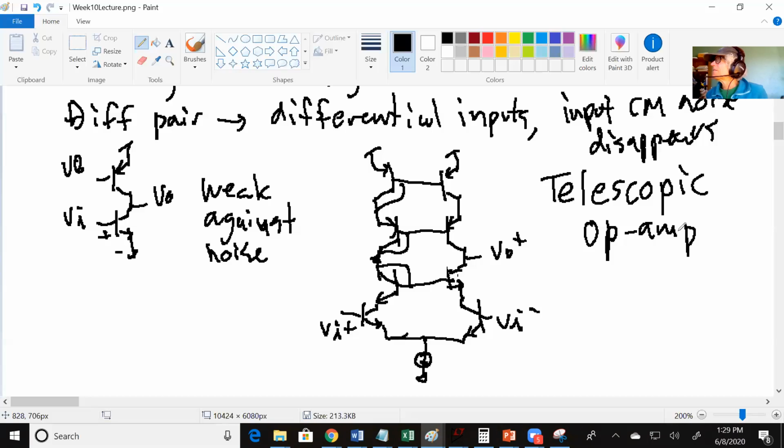Probably. So in EE 431, I don't know if anybody's going to take that in the fall, there is a maximum voltage for a particular transistor. When you want to make an integrated circuit, you want to make a chip, you find a company that fabricates the chips, and you ask what's the maximum voltage I can use? They will give you a voltage, and you have to abide by that, or they won't guarantee the chip will work. Like we've had a 1.2 volt, 1.8 volt requirement from the fabricator. So often you can't really move the rails.